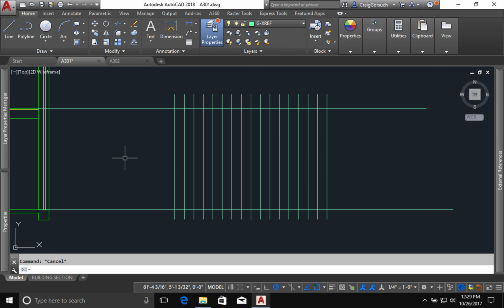Now I need 18 copies of this line from the top. We're going to get to a point where the distance for the riser height, which is just over 7 inches, we're going to make exact in a minute. But I'm going to start with a 6-inch riser, even though I know it's wrong. There is a method to my madness, I promise you.